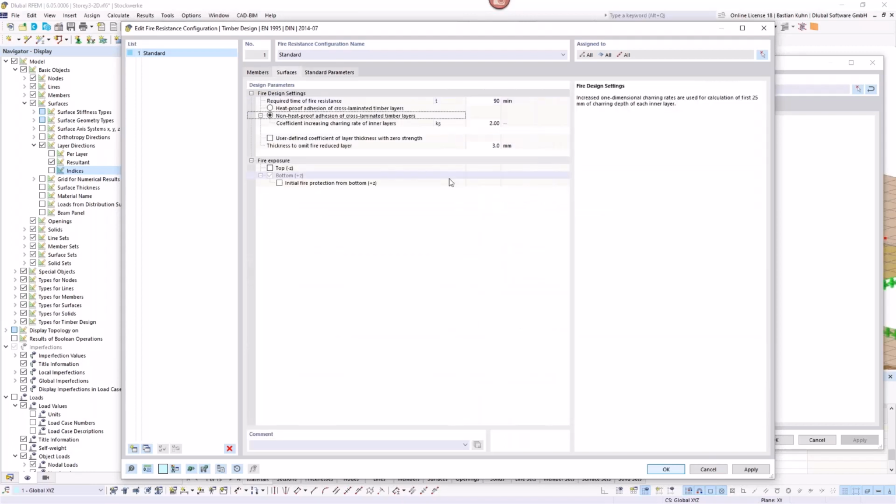The burning or charring rate for cross-laminated timber is similar to softwood, 0.65 millimeter per minute. So you say 0.65 millimeter per minute for the first 25 millimeter thickness. Then when one part of the structure or of the layer is burned, it comes into the area where the glue, the adhesion, works, in the connection of the two boards.